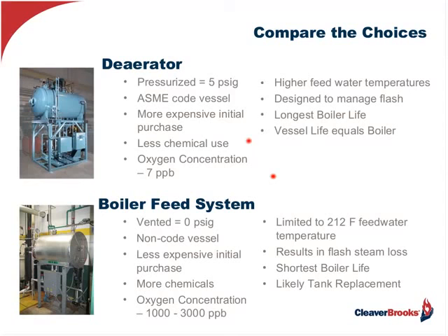But when you take a look at the amount of heat you capture, reducing the chemicals you're putting into the boiler feed water, and reducing the amount of water you're using to keep this system going, deaerators should be very, very seriously considered.